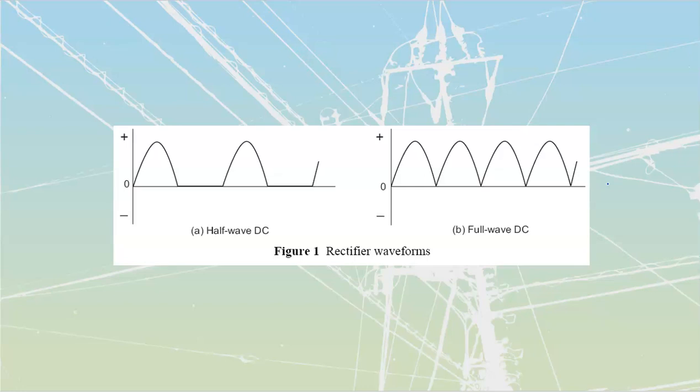The usefulness of these two waveforms really relies on the fact that they're going to be going down to 0 in a lot of cases, because in third year, you're going to cover a bunch of electronic devices that are going to shut off based upon minimum current, where we are going to be able to turn things on based on what time we want. So we could turn a waveform on over here, and then it's going to conduct, and then it'll automatically shut off once we hit a value of 0. So having these types of waveforms allows us to have what will be referred to at that point as automatic commutation, or shut down, which means that we could have a blip through, and then we could just leave everything off, and until we give the next blip, we would not get any power out of them. It makes it a useful, controllable type of voltage.